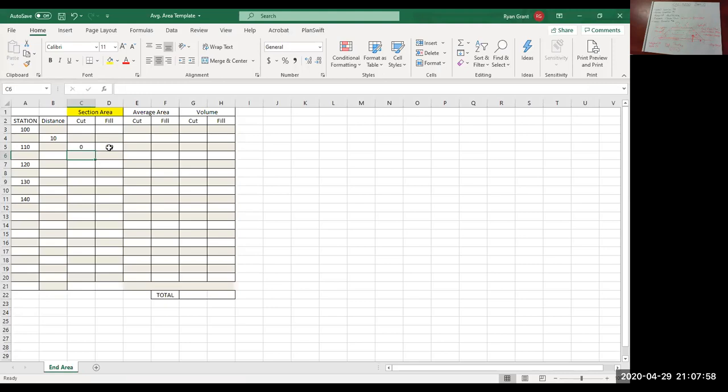So you would do this for each station. I'm going to give you also 0 plus 120 so I can show you how this works. At 0 plus 120, there's also no cut, and there's a fill of approximately 1.7. If you get slightly different numbers for the rest of these than I have in my answer key, I won't mark you wrong as long as they're similar numbers. Okay, so you'll fill out all of these white cells with your calculated end areas for cuts and fills.